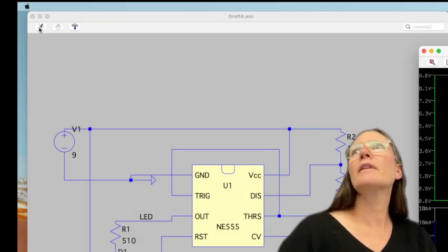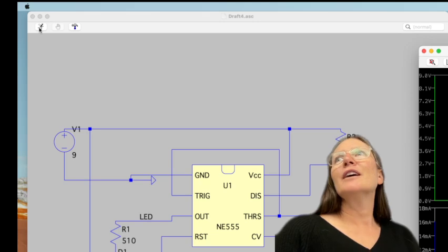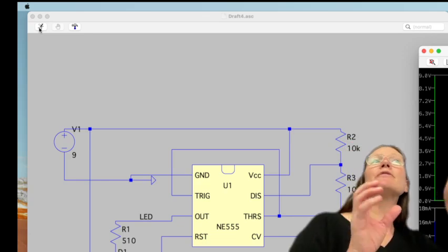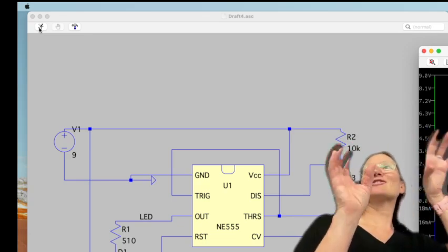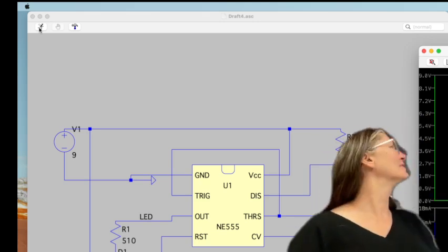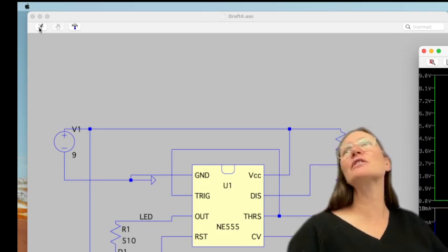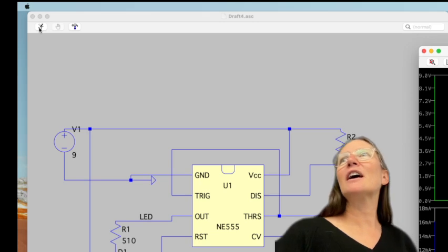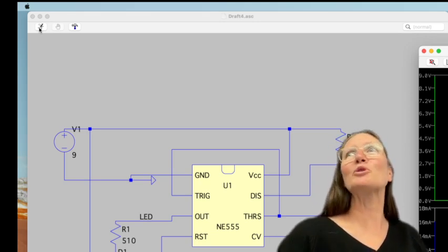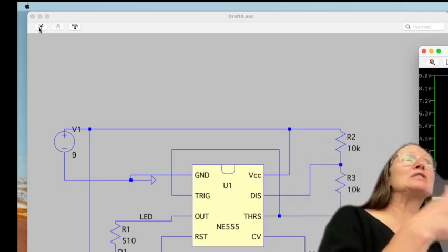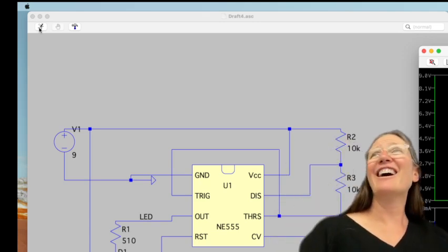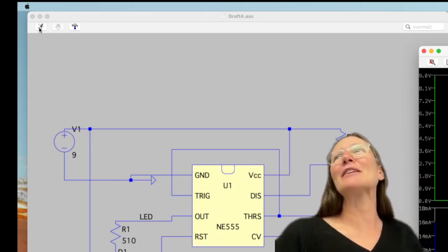So is the capacitor just storing energy? Uh-huh. So in 1230, we'll talk about the capacitor, and you'll learn how to actually create this timing. And it's R times C. So you work on figuring out, if I fix my R and I'm just changing my C, why is that increase or decrease making it faster or slower? We'll talk about that in 1230. But for now, understand that if I just want a specific, fast clock, I can decrease that and make it faster.